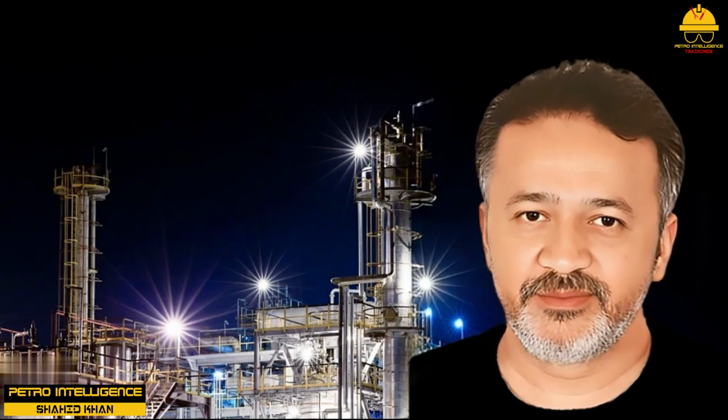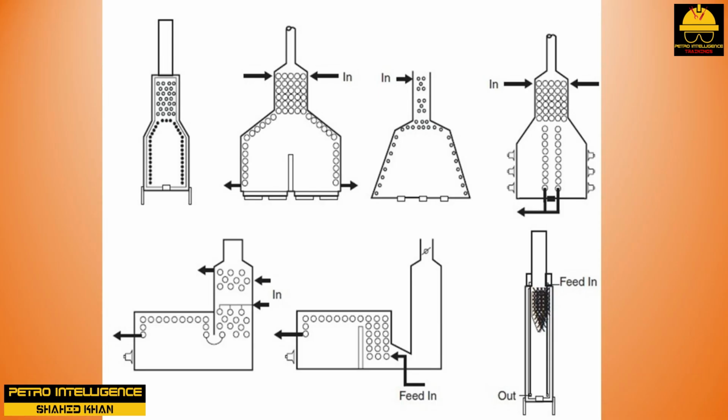Reaction furnaces. Reaction furnaces are simply fireboxes containing an arrangement of tubing through which the reactant stream is passed. A fuel and air mixture is introduced into the brick-lined firebox, which provides the heat for the reaction that occurs in the tubes. Most furnaces are used to crack hydrocarbons. However, there are reformer furnaces in which steam and methane are reacted together to get synthesis gas, carbon monoxide and hydrogen. For the catalytic cracking of hydrocarbons, catalytic pellets are packed in the tubes inside the furnace.